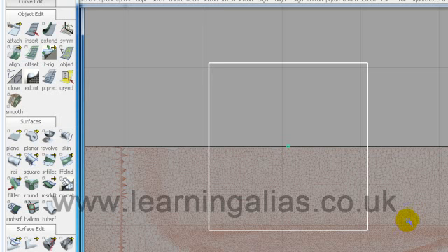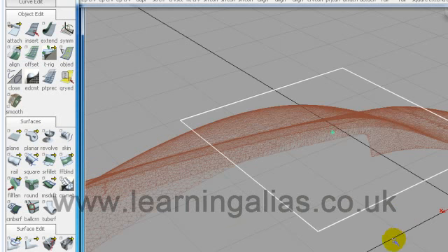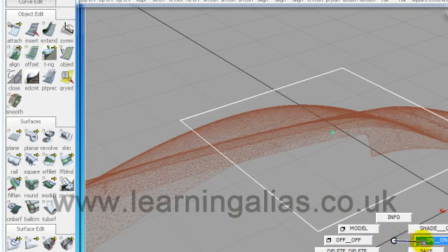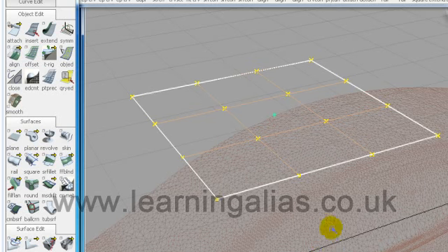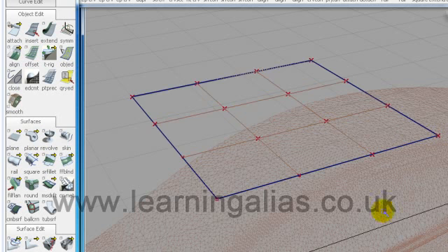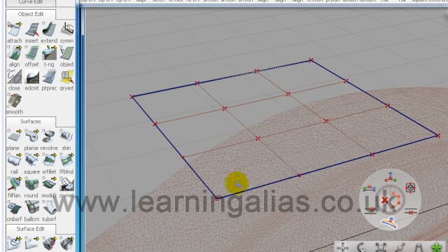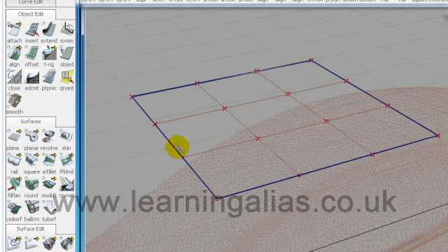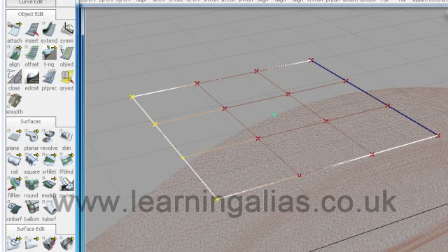Go to F8. And we can't put cross sections on a flat surface, so what we need to do is go into Transform CV, and this time I'm not going to use NUV because it's too big a distance and it distorts the hulls. So I'm going to use XYZ, which is actually probably better. And I'm going to turn the sensitivity down.